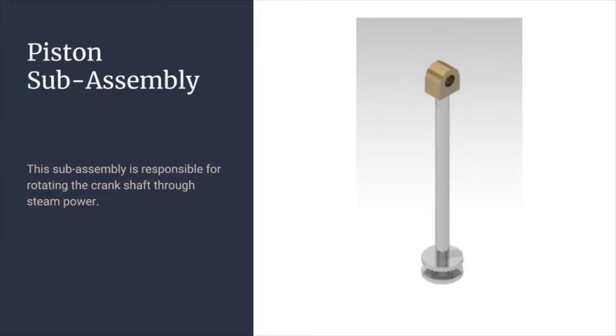The most difficult aspect of this part was that the top part, the gold portion, has a hole that goes through to let the rod in. Well, for some reason, CATIA oddly forms that hole, so you have to create a plane that is right at the end of the hole, and then when you create the hole command, you just say up to plane and select that plane as the end of the hole.